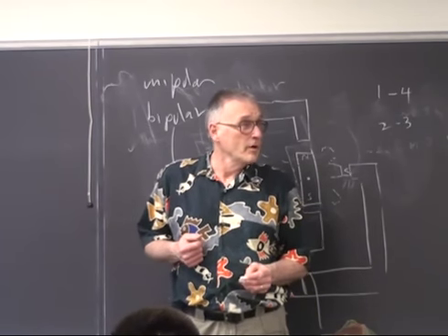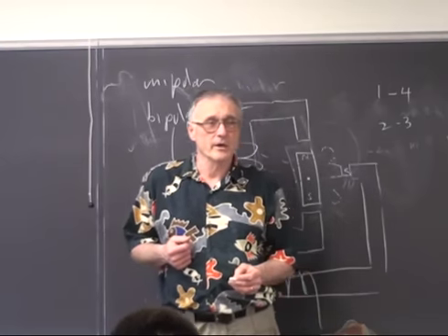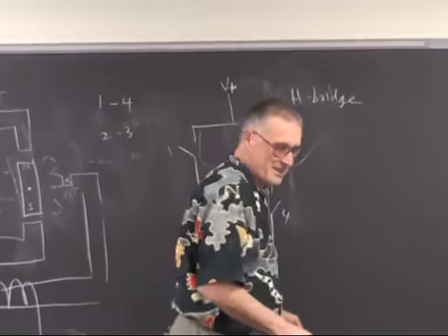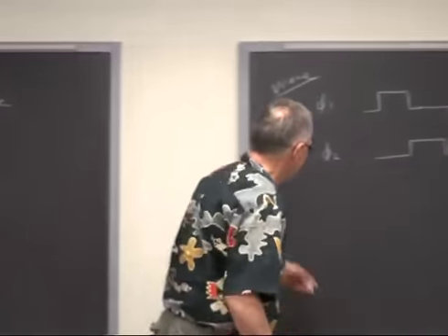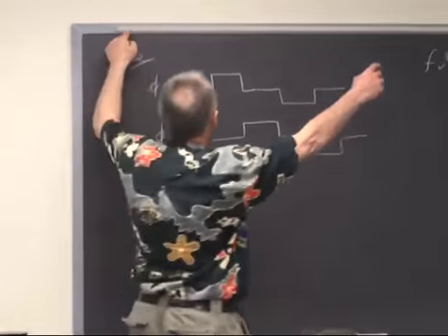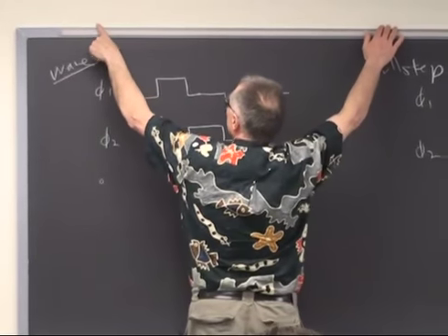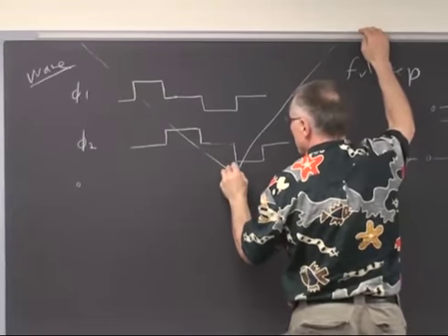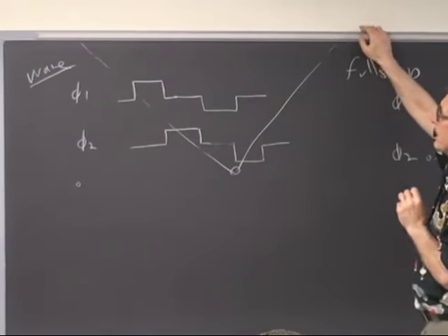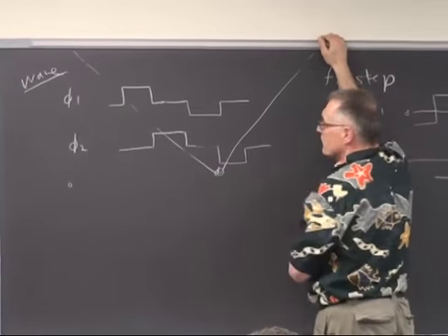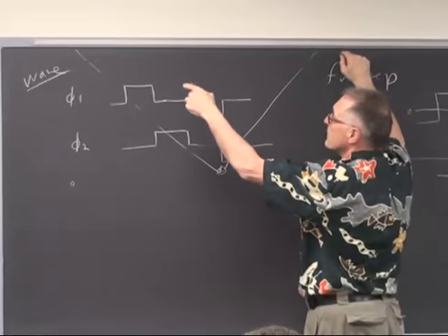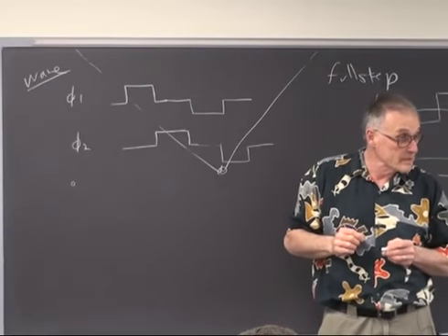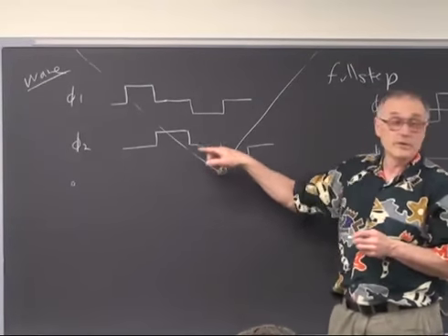We've had people do open loop control in the past where you set up the system. This was an interesting use of it. They took two stepper motors, put them up here on a blackboard, on a whiteboard actually, and ran fish line down to a magic marker, and then they positioned the magic marker over the X, and then after that the motors ran open loop. They didn't measure the position anymore. They just knew that they were producing enough torque not to slip, and they could move that pen around and draw on the board.